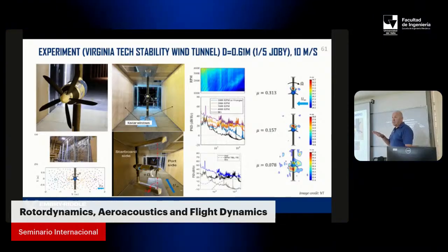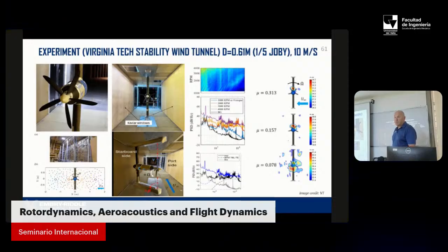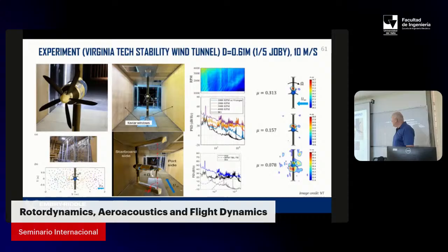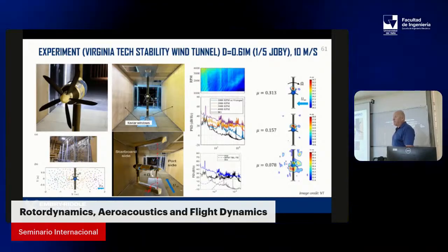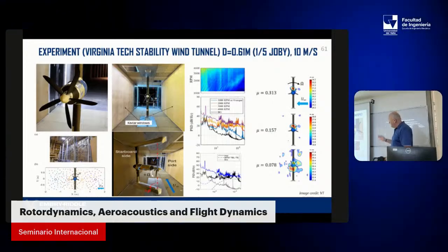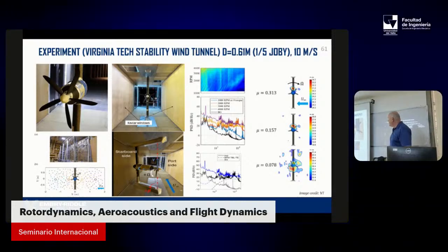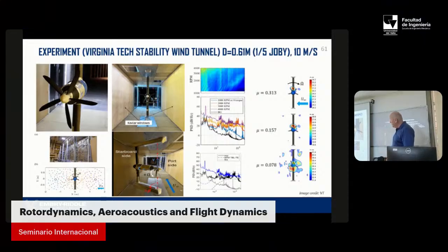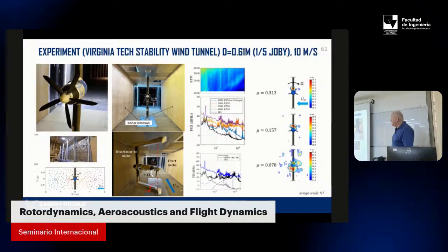The beamforming technique is a very interesting technique, which allows you to identify the source of noise. If you have measurements on different microphones, you correlate all of them, and you can understand where the noise is coming from. It's like an inverse problem. This is the thing which people do. They developed this method, and not that long ago it became mainstream, but they measure this and they can see where it is coming from. But they cannot explain all the phenomena. For instance, they found some tonal source, and they asked us, please do some numerics.